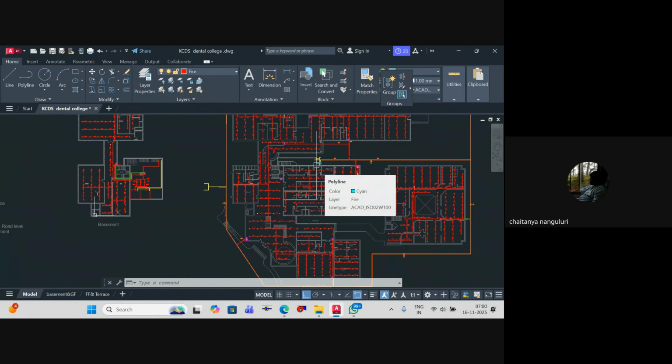But as per NFPA, as per the building dimension, they'll ask for two connections, oppositely diagonal, directly into the ring main. If the plot area is so and so as per NFPA, then according to the length of your building, more than one might also be required. In that case, diagonally opposite is what you have to provide, two numbers into the ring main. That is as per NFPA, but not as per NBC or IS codes.